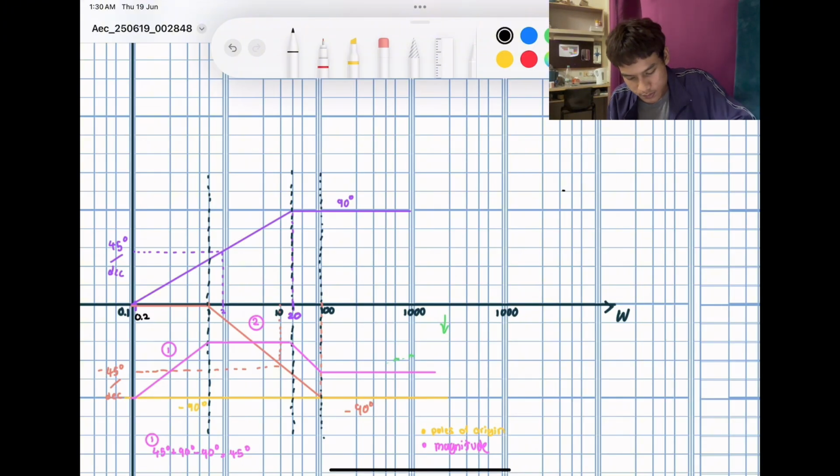So for your slope, right now you have a total of 2 decades from here to here. For 2 decades you will reach 90 degrees. So for 1 decade you will reach 45 degrees. This states that the angle of the slope is 45 degrees per decade.